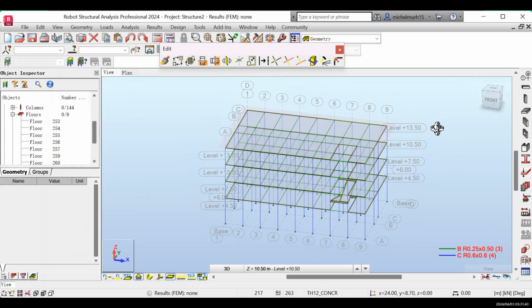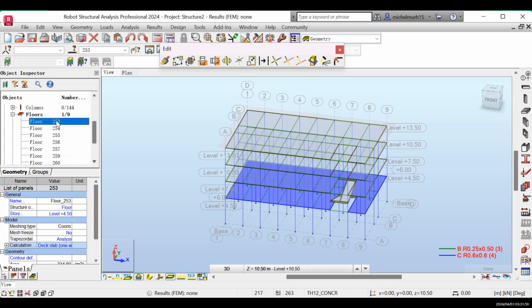So what to do? In this case, it's really simple. Just press escape to remove the zooming command, right? And go on this menu here, right? We have flows. Just extend flows, and as you can see, if I select this flow, I can see the flow selected, right? I just need to select the staircases. It should be 5 flows, right? 1, 2, 3, 4, and there's another support here, right? So it's supposed to be 5 flows, right?